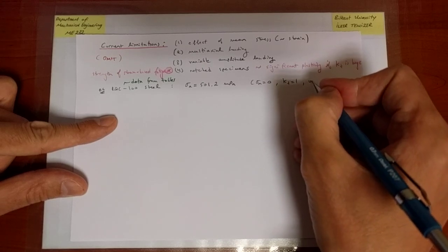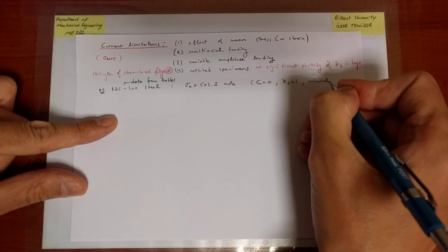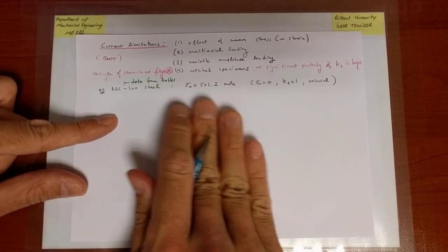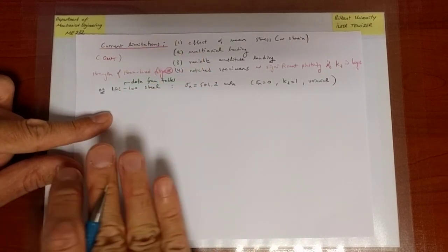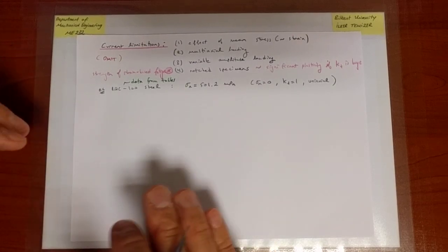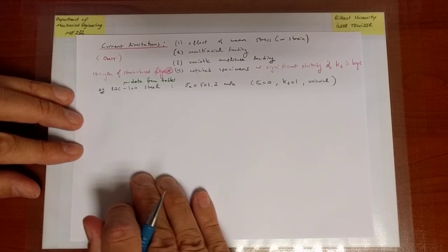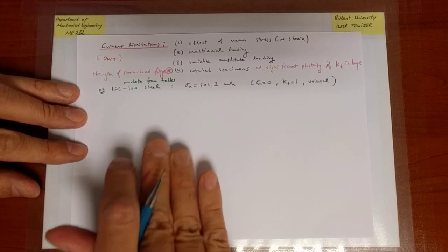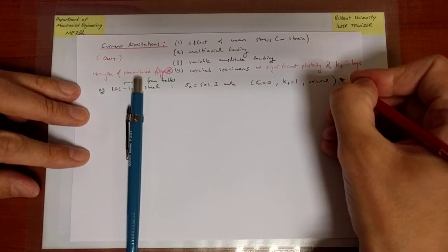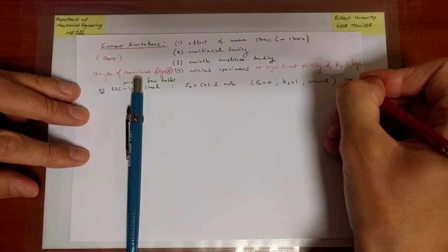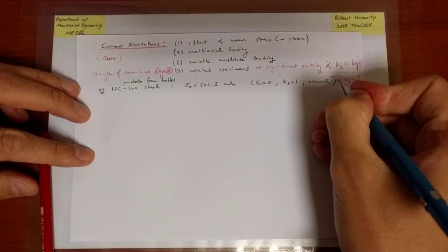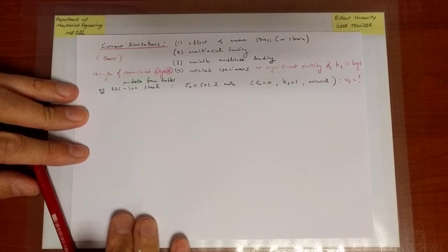And finally, we're looking at uniaxial loading. There is no other stress. So it's exactly the approach that we are discussing, and the amplitude does not change. So it fits these limitations. And that's what the Coffin-Manson equation in its original form stands for, just like the Basquin equation in the case of stress-based fatigue. Now, the question is simple. What is the number of cycles to failure? That's what we would like to find out.